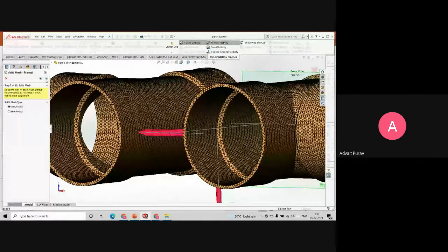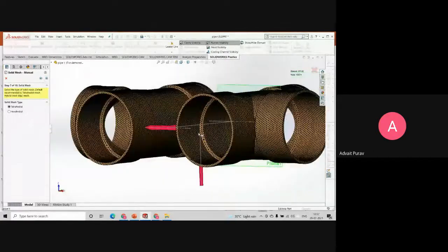But you definitely need to know which mesh you are using and why. Whatever I had read about hexahedral mesh, I might be wrong as well sir, you can correct me on this: according to me, hexahedral mesh is used for parts which are not very intricate or complex, because its computational cost will be higher. It also depends on shape conformity, what the structure and design of the shape is like. That is correct. Okay sir, okay sure, thank you.